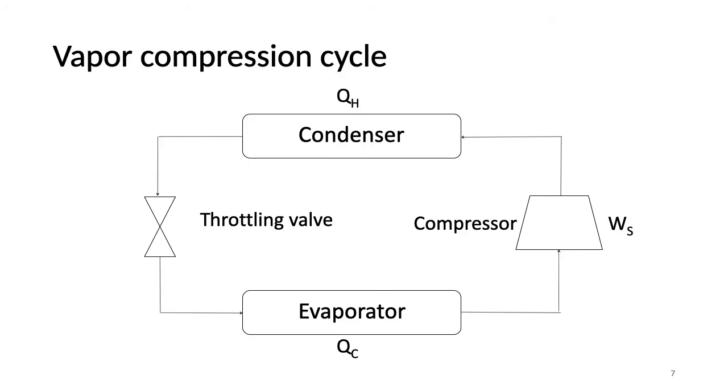Vapor compression cycle. Heat pumps, refrigerators, and freezers operate on the vapor compression cycle. That is a reverse Carnot cycle. But how does this cycle operate? Work is put into the compressor to raise the temperature of the working fluid by compression. Then cool it to liquefy at high pressure in the condenser. Next, drop the pressure isentropically through a throttle to obtain a cool fluid. Finally, boil it off in the evaporator at a low temperature.